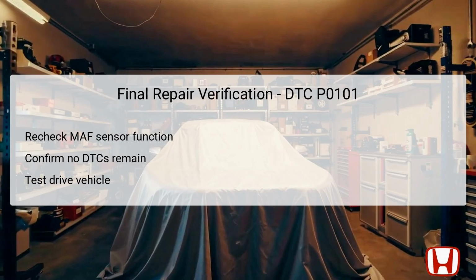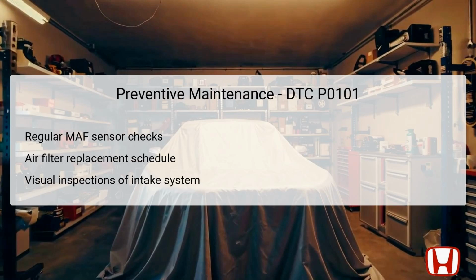Additionally, it is crucial to confirm that no DTCs remain in the system, which indicates all faults have been addressed effectively. Following this, taking the vehicle for a test drive under various conditions allows technicians to observe MAF functionality in real-world scenarios. These steps ensure that repairs have been successful and that the vehicle operates at optimal performance levels, enhancing reliability and efficiency long-term. Preventive maintenance is essential for avoiding future occurrences of DTC P0101.